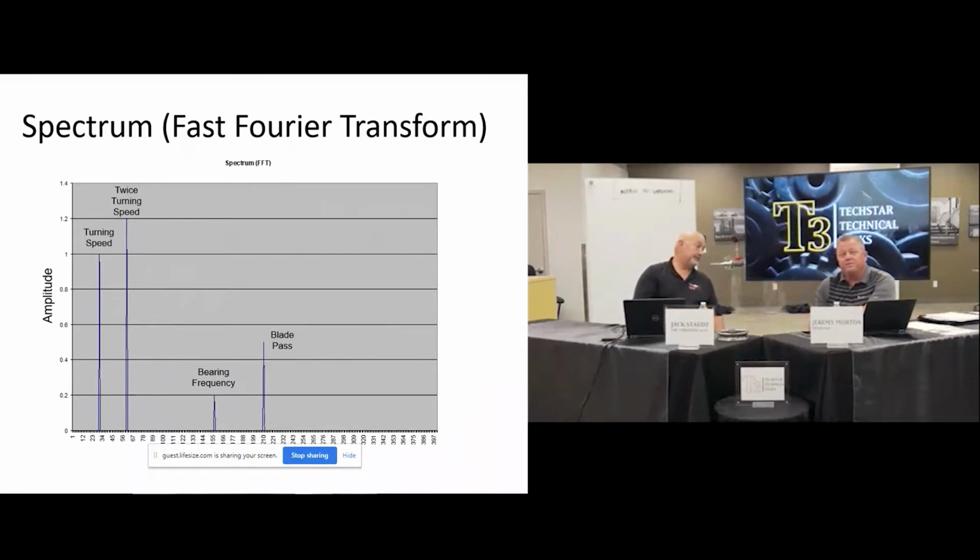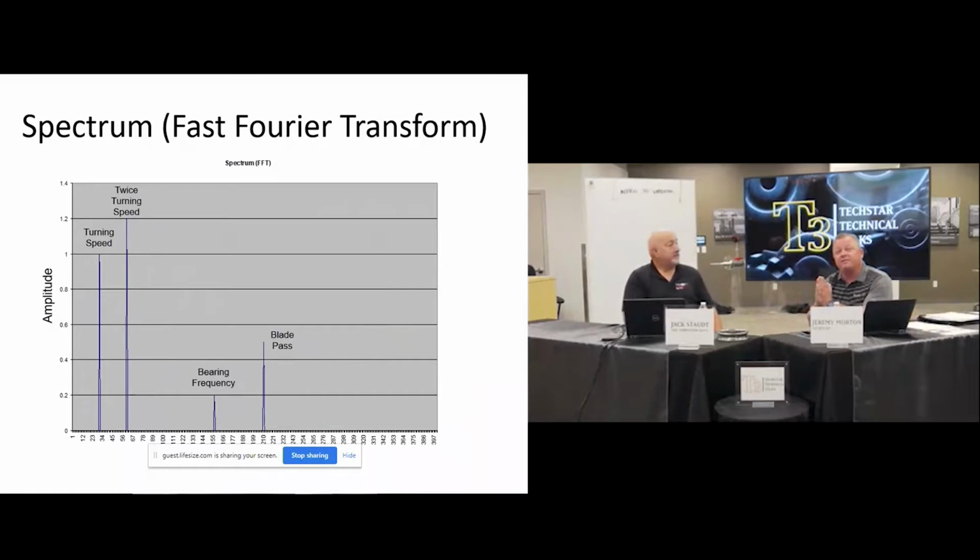I guess an important point too, this is a half spectrum that you see there on your screen. Sorry, I may have lost you guys. Let's see here. What just happened? It closed. All right, there we go. That's a half spectrum that you see. So basically that's all your forward precession vibration. You'll also hear there's a full spectrum, where on your x-axis, where it's 0, you'll have negative frequency components as well that can be different sorts of machinery failure and things like that cause those. But just for your own reference, so make you aware of it. And we're going to cover some of that.